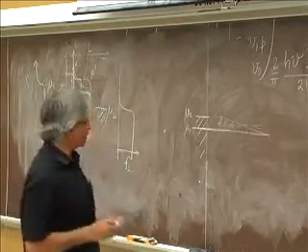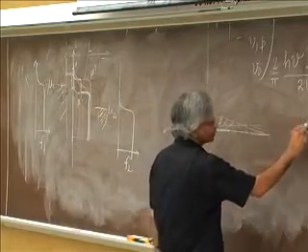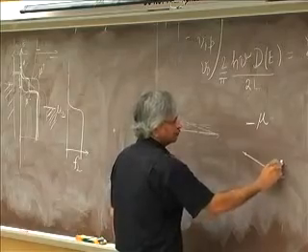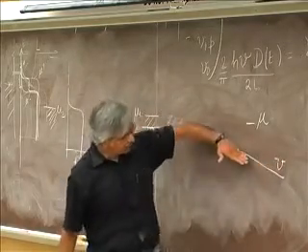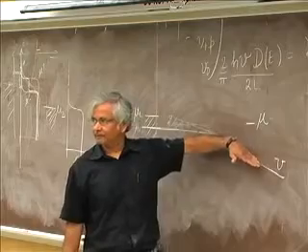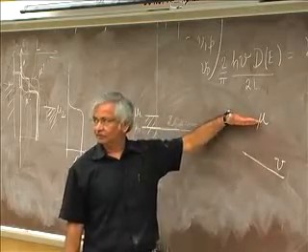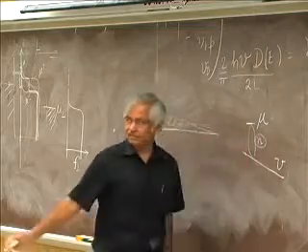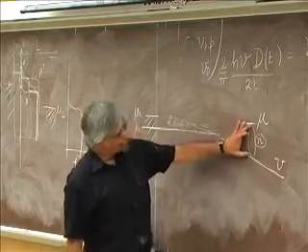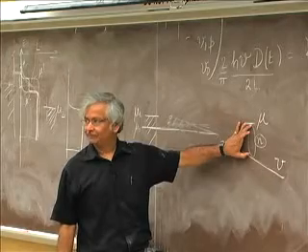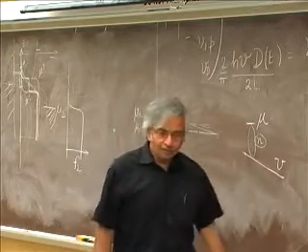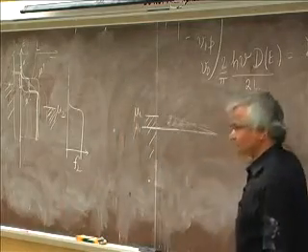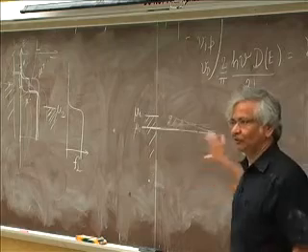So the picture I have in mind usually is that there are two things. One is mu, the other is u. The u has to do with how the band edge moves, and mu tells you how far it is filled. The difference is proportional to n, the electron density, because you have all these states to fill up. What tends to happen is that the Poisson equation likes to keep this constant, because it really likes to get rid of extra charges.